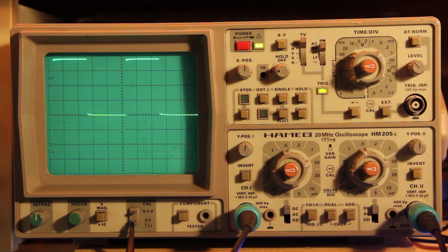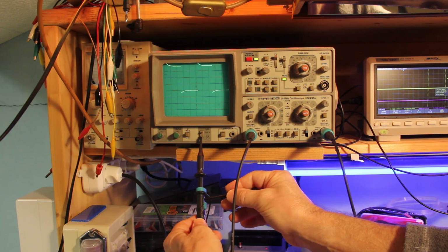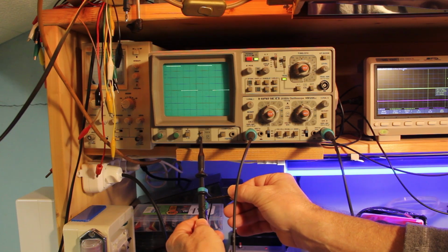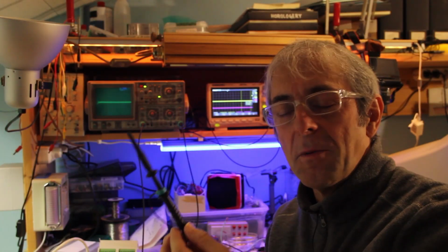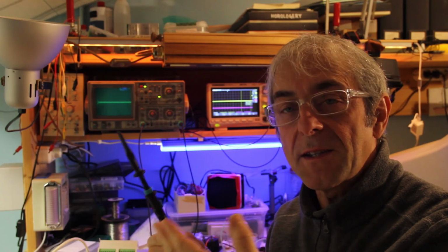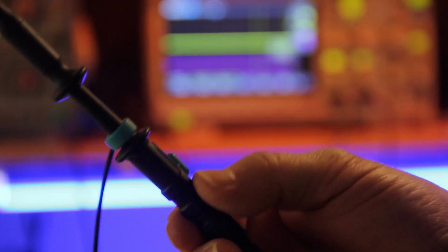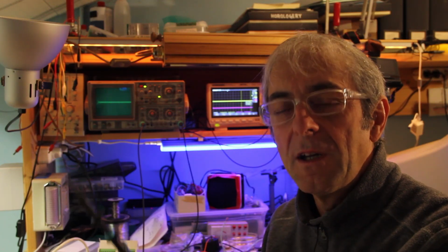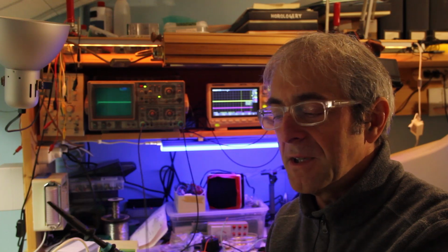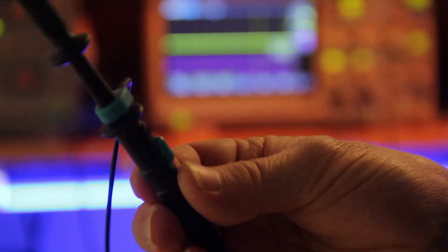As you can see here, I demonstrate two different improper calibrations, while the proper adjustment is when we see a neat square wave. It might take a while. It is important to remember that this calibration is meaningful only on attenuated probes, attenuated by 10 or by 100 or more, because there is no compensation on probes that are not attenuated.